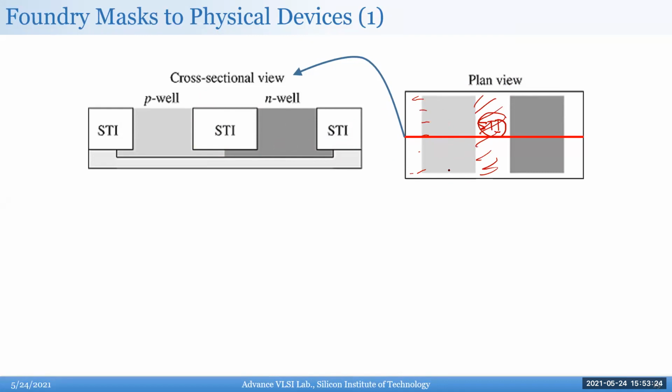They'll take the P well mask and the N well mask, and do what's called ORing of the mask. Wherever there is a P well or N well, those areas will be masked. Everywhere else, the STI will be done. Same process again: take the mask, do photoresist, shine UV through the mask, etch it, do the STI mostly through oxidation. Trench it first, then do the oxidation, remove the photoresist, and then you'll have this, right?